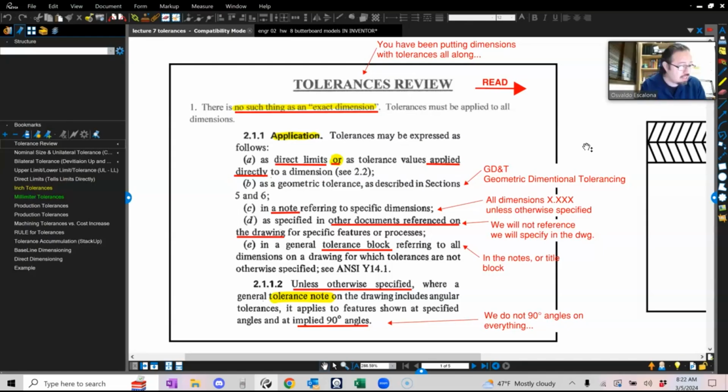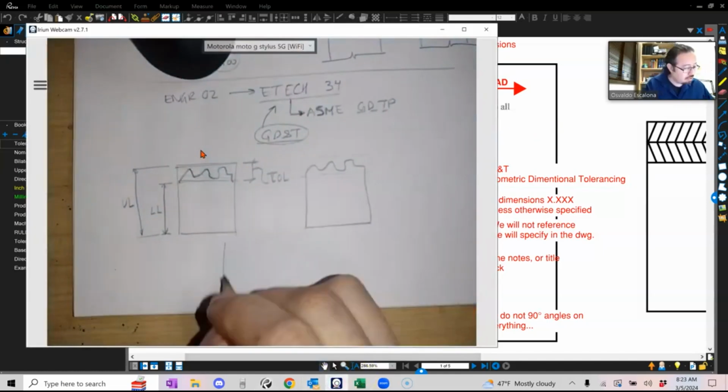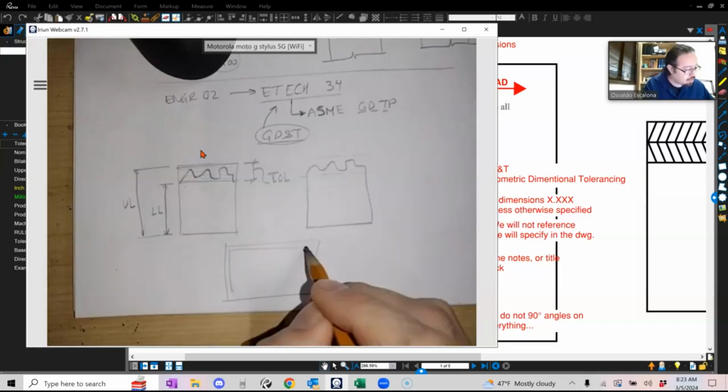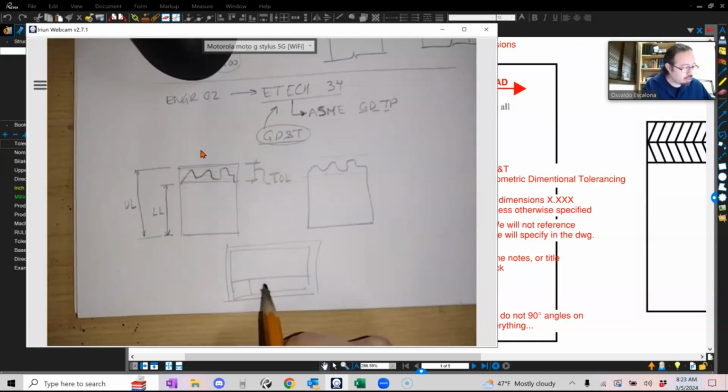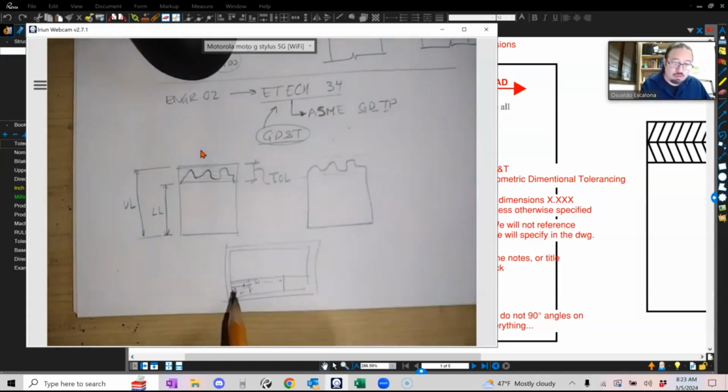You can put it in the title block. I've seen it many times. If you remember, your drawing title block looks like this, and it has the border, and then it has a block, so Kings Delta College, and so on. Many manufacturing or mechanical companies have a kind of disclaimer, and somewhere right below it, it has the tolerance: all linear dimensions, all angular dimensions. They also put a profile tolerance, stuff that you will not learn until you take the course. But again, it will be on the title block itself.